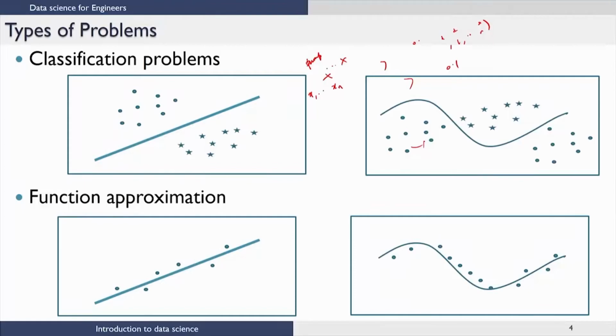And if you have legacy data or historical data where you have been operating pumps for years and years, then you know that if these variables take values in this block, then everything is fine with the pump. So, I write n for normal, and then you could have a block of data, and that data might have been the data that is recorded whenever there is a particular type of fault in the pump.